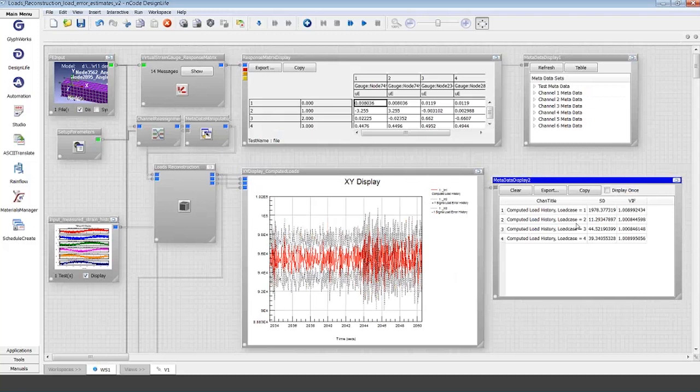We could also see it in some of these other terms that we looked at earlier, like the strain gauge sensitivity matrix. There's a thing called the VIF, the variance inflation factor, that says how collinear the loads are if we use this strain gauge sensitivity matrix. So we have various metrics built into this calculation, so we can look at this not just in a deterministic way, but in a probabilistic way, because we know that we have variability in measured strains.